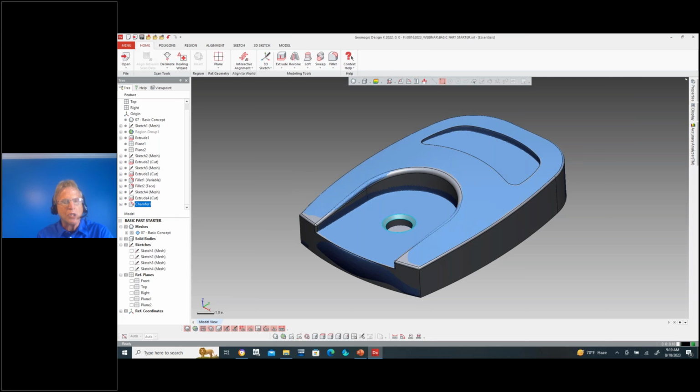So with your scan data, as you reverse engineer, one of the reasons you can apply driving dimensions to the model is you can go ahead and set dimensions to be the correct dimensions, meaning if something says it's a 0.998 diameter, you can go in and force it and say, no, that's actually supposed to be a 1-inch diameter.